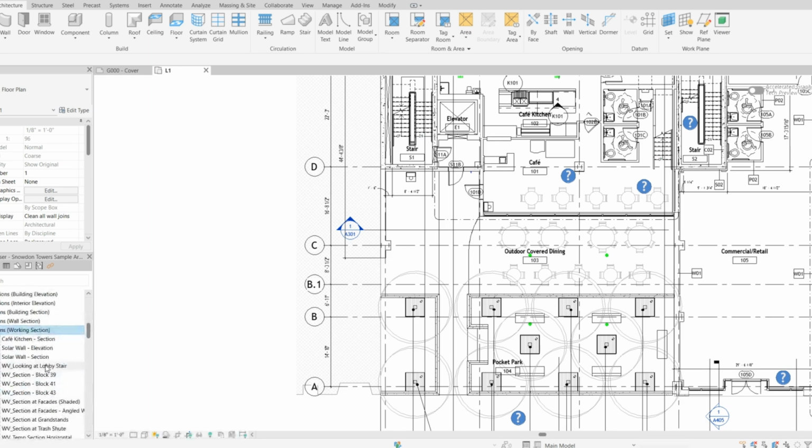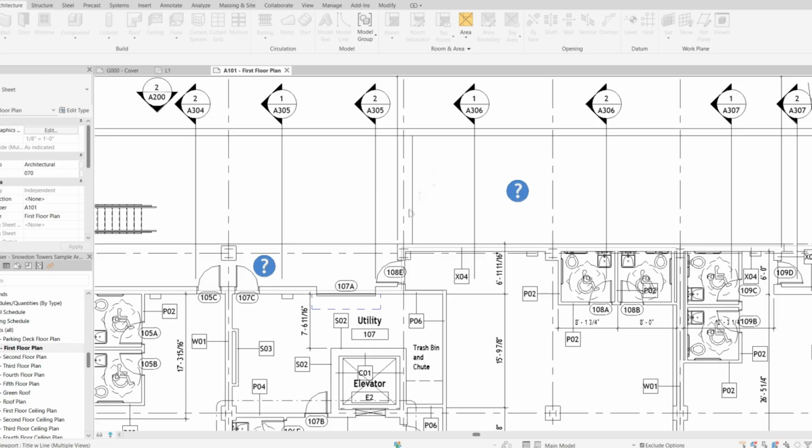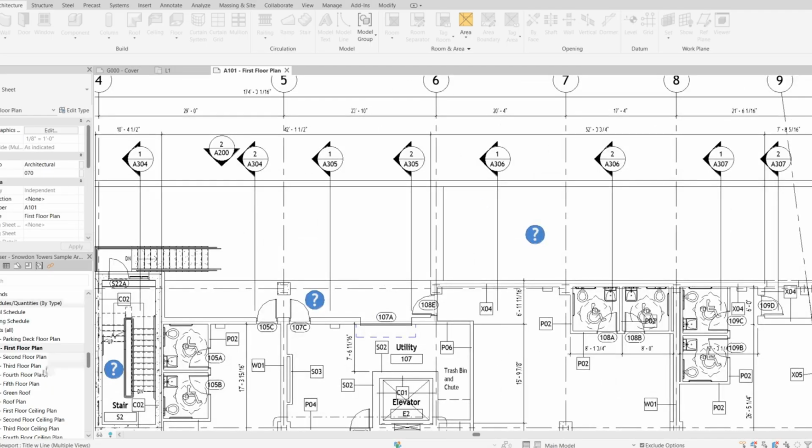So in this session, we'll cover how to quickly switch between imperial and metric units in Revit, how to set units for the entire project, how to override units for specific dimensions or views, and some best practices for aligning unit standards when collaborating with freelancers or external teams.